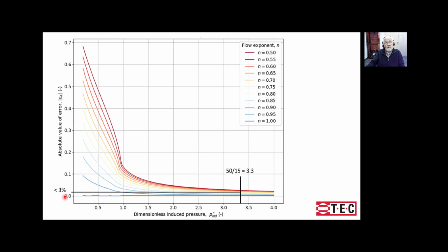We certainly will use it in our software where we estimate what the plus or minus values are associated with, say, CFM50. You might get 1500 CFM50 plus or minus 100 or 50. This will allow us to better estimate what that plus or minus number is, and we hope it'll get used by people that are involved with standards writing to make it easier to do a test on a day when it's cold out and there's a lot of stack effect.